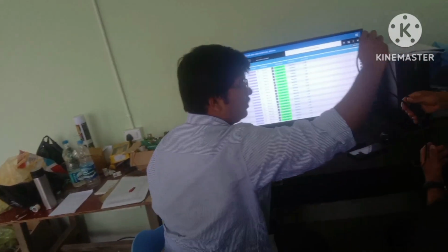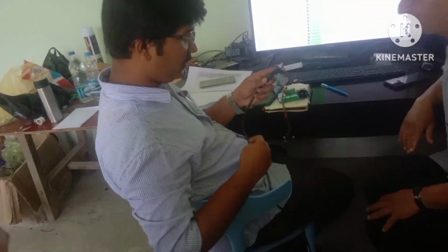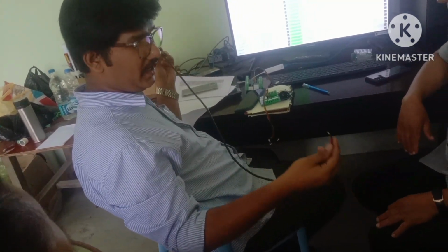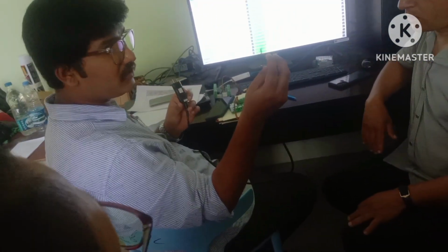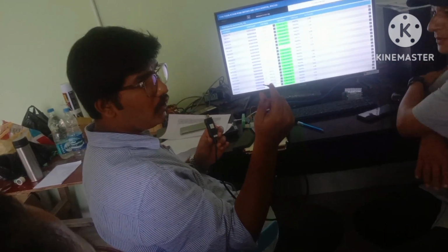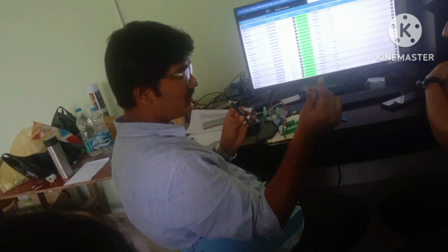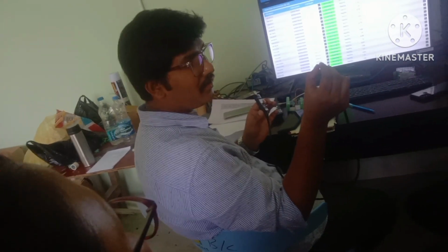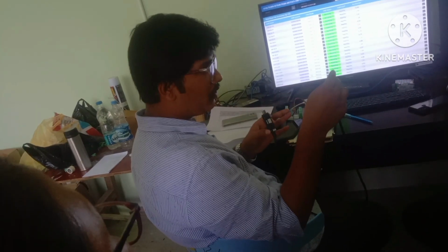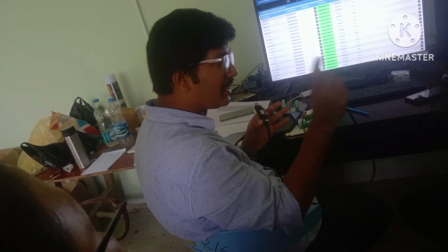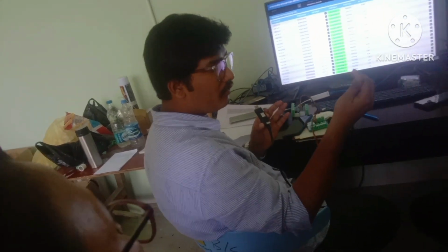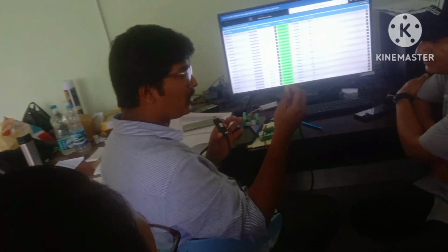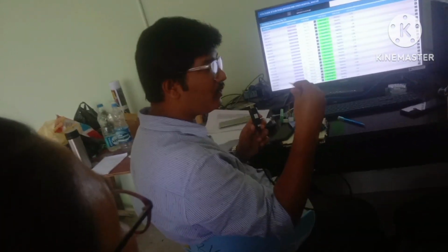Oh, this. So if you see, this is a converter, basically an RS485 converter. Of these two wires, red stands for positive and black stands for negative. This is a very big risk, because if by any chance these two wires get connected, there will be a short. No blowout or anything, but that will damage that particular IC. So we have to always make sure these two wires are not shorted or connected in between. They should always be isolated.